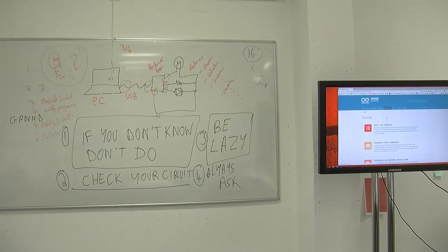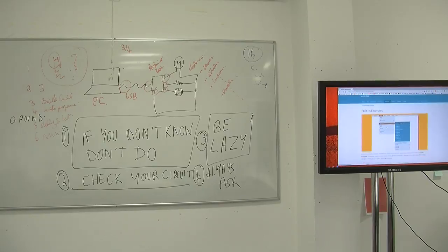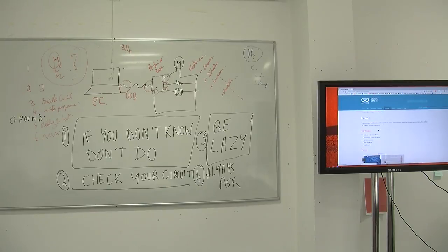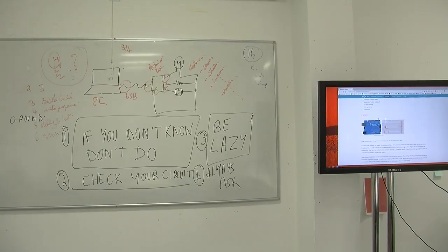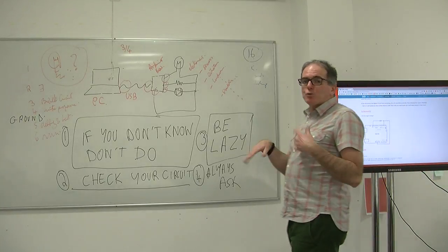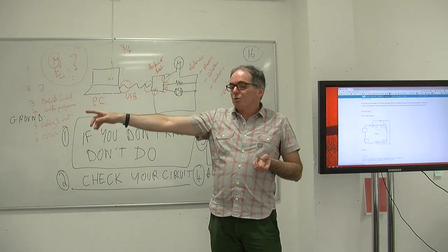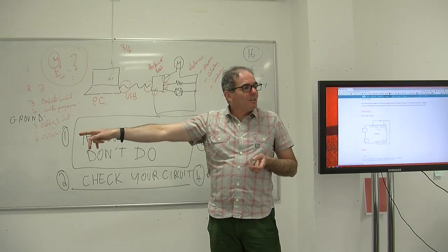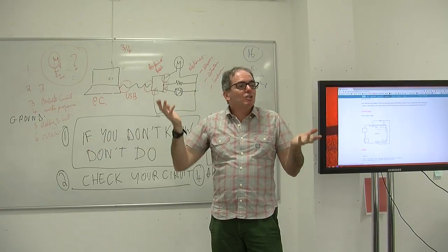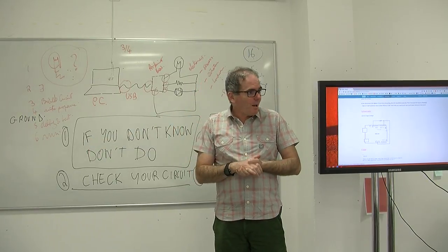So if I go into the tutorial, built-in examples, there might be something. I don't know, I'll have a look. So I have blink, I have digital, here I have button. And here's a circuit where I have a button. So again, because one of the reasons to be lazy, I can use this and the one with the LED, and I have to find a way of combining them to program the LED to blink when the door is open. And essentially, that's what it's all about.